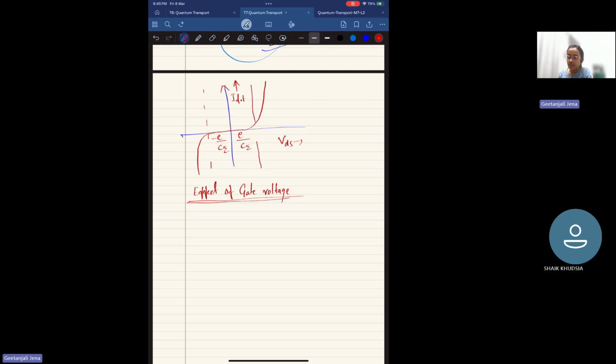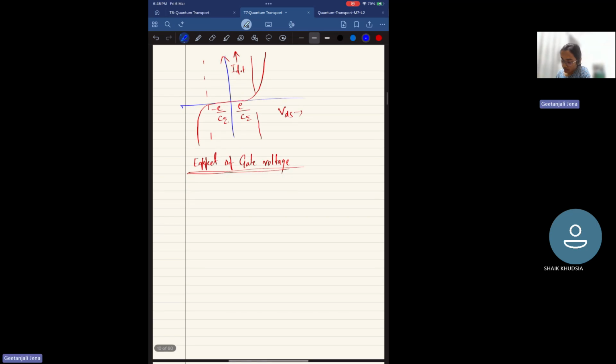And also we'll see tunneling of charge carriers one by one whenever the parabola touches at the charge degeneracy point. What I mean is that, similar to the single electron box case, we can write the electrostatic energy as the induced charge because of this gate and the charge in the conducting island, divided by 2Cσ.